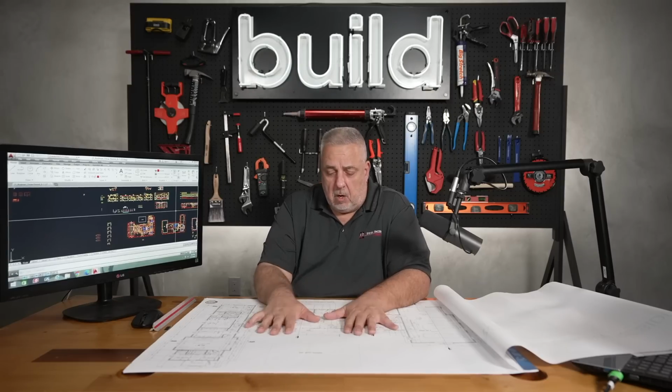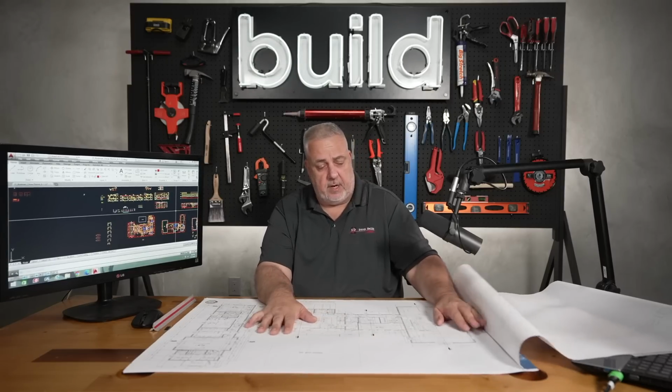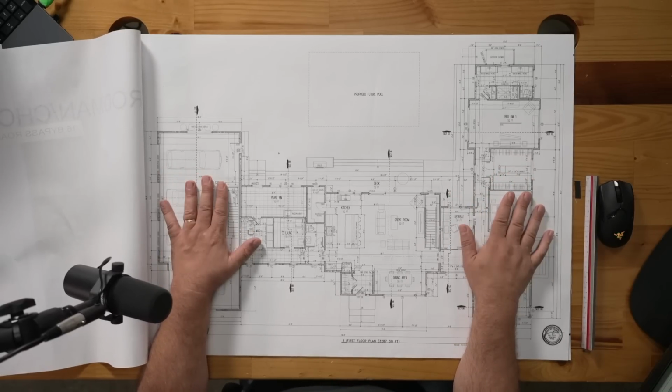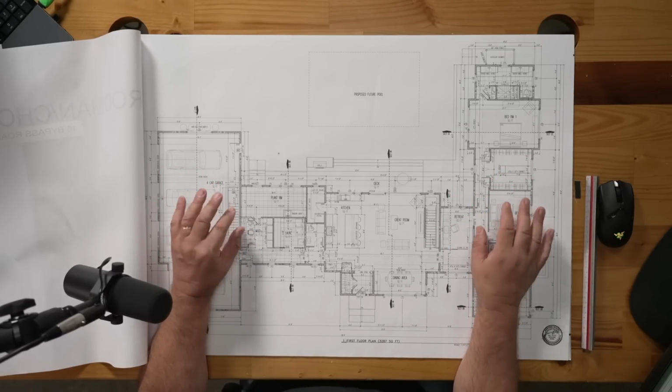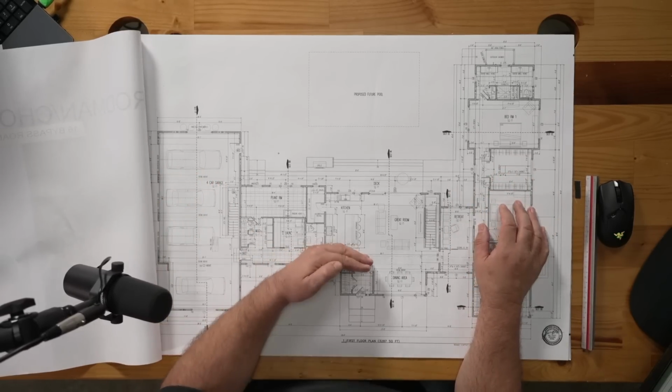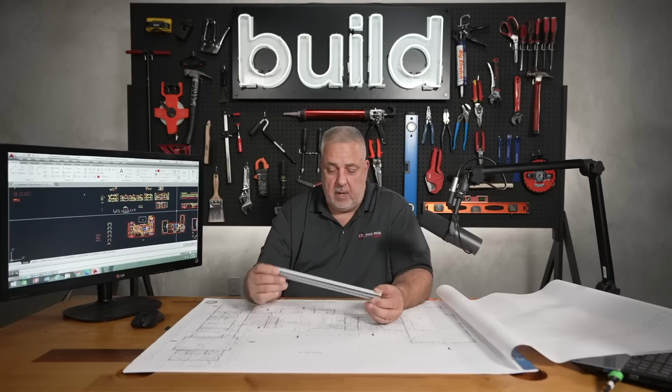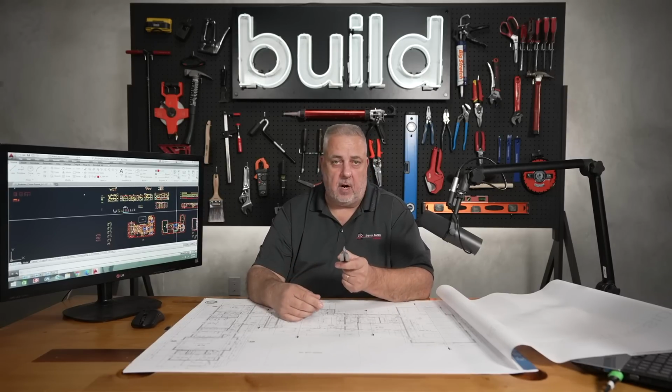But, you know, floor plans, you can see this one here. The entire floor plan does fit on a sheet. Sheets are 24 by 36 inch. Those are D-size sheets. Floor plans are typically drawn to 1/4 inch scale. Now, what does 1/4 inch scale mean? You're familiar with an architectural scale.